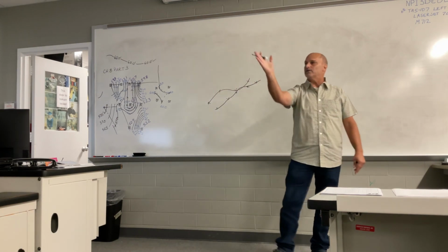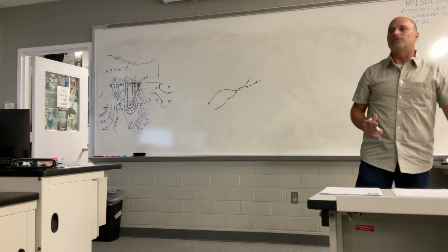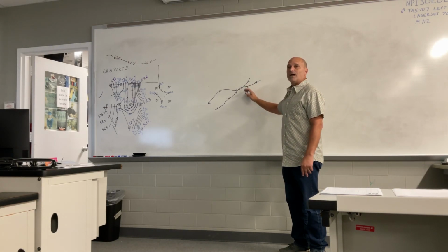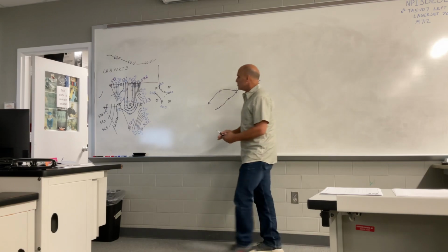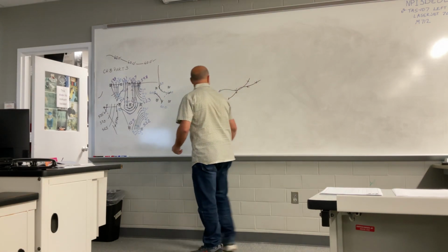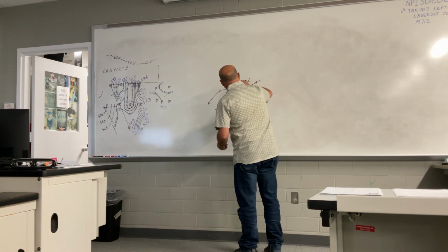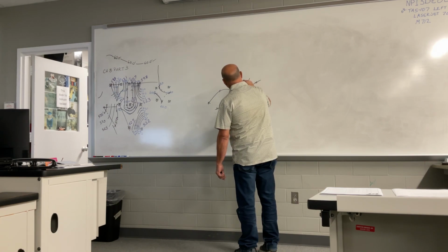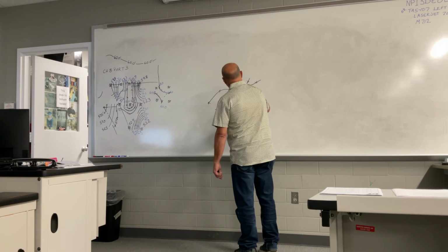AutoCAD makes that flowing curve through there. We know those elevations don't flip sides like that. By having those extra pick points, so if you had extra points when you were placing that spline, you could then select that spline. It's gonna pop up those blue grips, and you can just move those grips over to there and force AutoCAD to make the contour or the spline go in the direction you want.